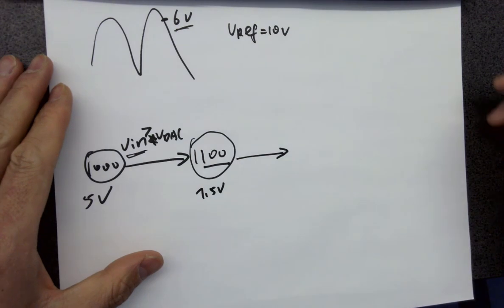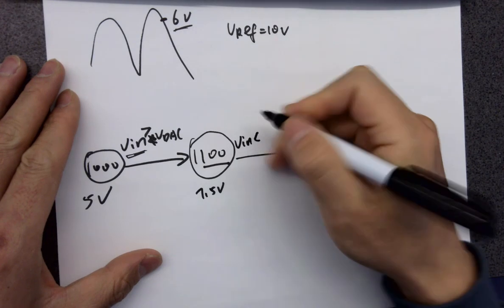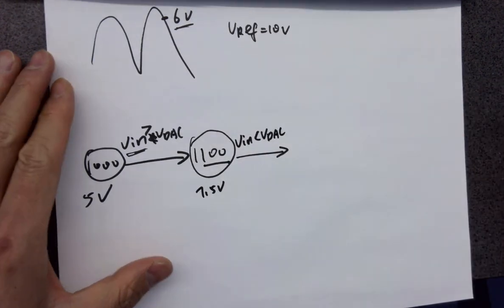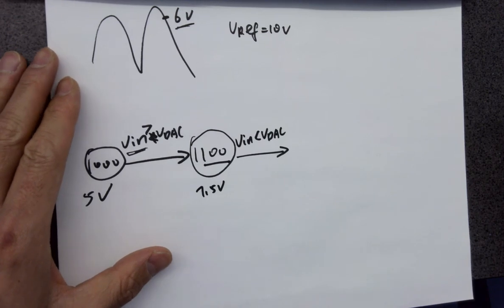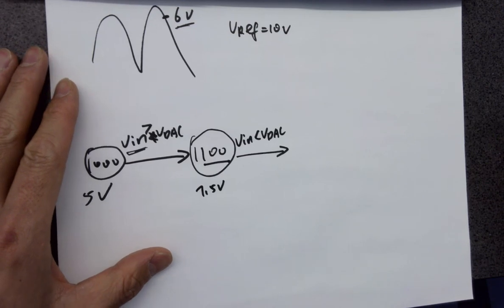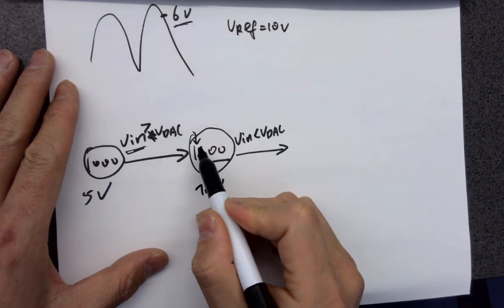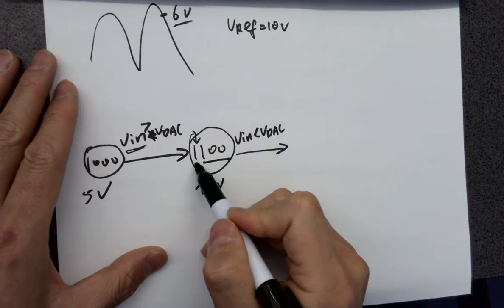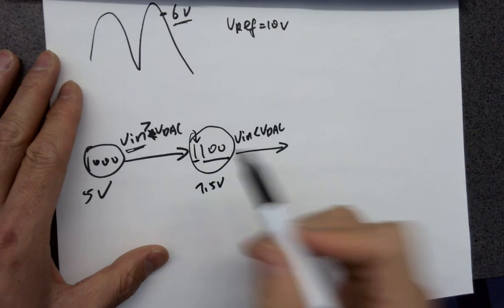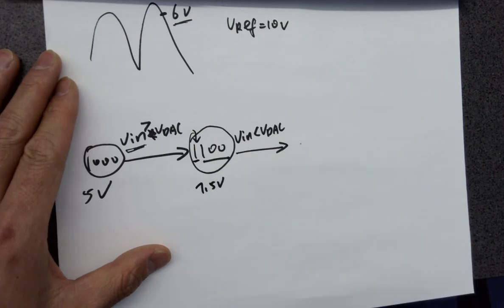Becomes the next VDAC. So now V in is smaller than VDAC. What's the next digit? What's the next code? Keep in mind, you shift this one more time, you're plugging the new number in after the last one, but you are shifting the original code to the right. So what's the next one?